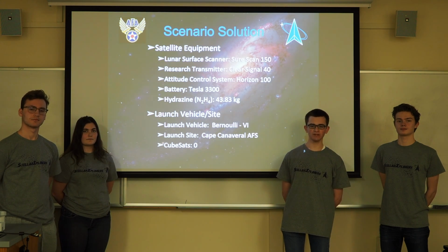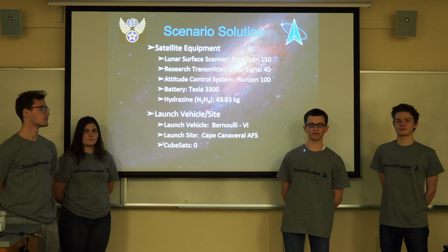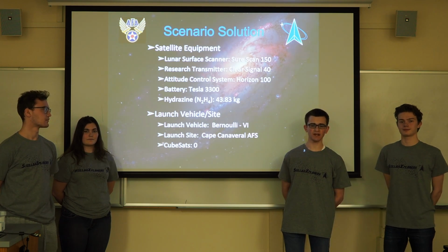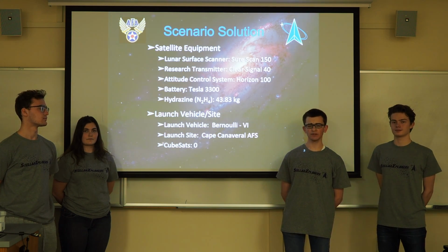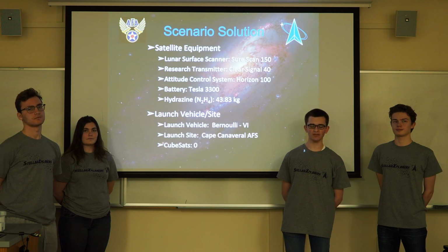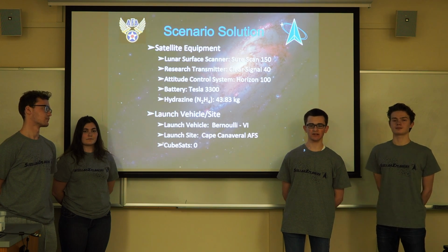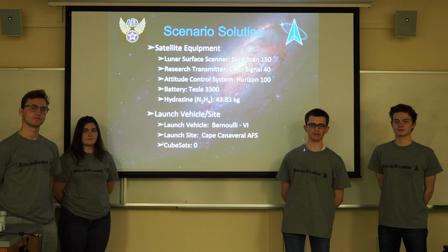For the 2-week mission, we will be using a Tesla 3300 battery, which, for again, a relatively low cost and weight, will satisfy our needs for the mission. Lastly, we will be carrying an additional 44 kilograms of hydrazine with us. That way, we can correct the trajectory as we orbit the moon if needed to again obtain the highest quality images of the lunar surface.